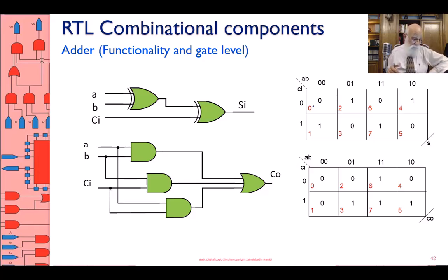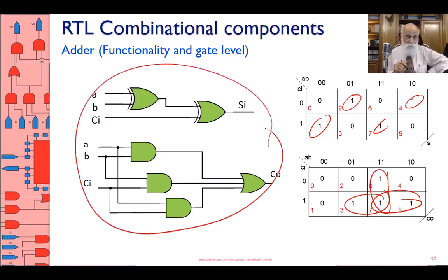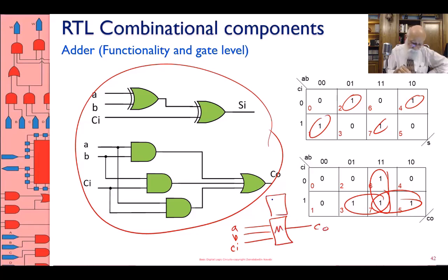What I have here is the A, B, carry in and produces the sum. That is the odd circuit. Okay, odd circuit. Down here is the majority circuit, which is this. Together, I put these together, a circuit with A, B, CI. Majority gives me carry out. Odd circuit gives me the sum. Okay?